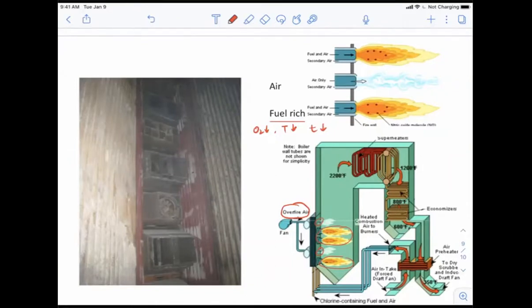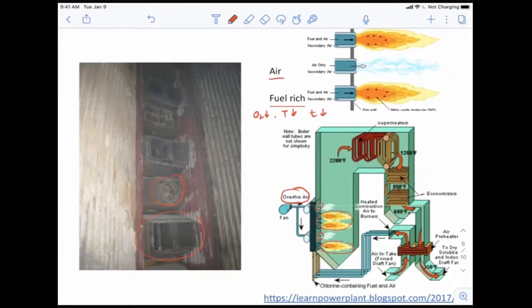So basically, what it really looks like in a co-combustor is that, let's say this is our nozzle, right? You're going to introduce the coal in there, and then this is a fan, right? So the fan here is going to introduce those overfire air that's right above these coal nozzles, to basically consume the rest of the hydrocarbons. So the overfire air will just react with the remaining coal so that we don't waste any energy coming out of the coal. Okay, so this is how the entire boiler looks like.